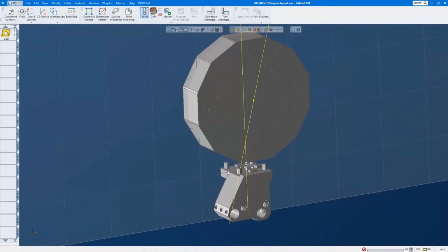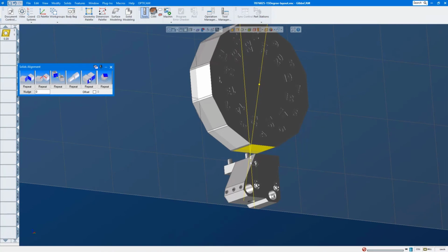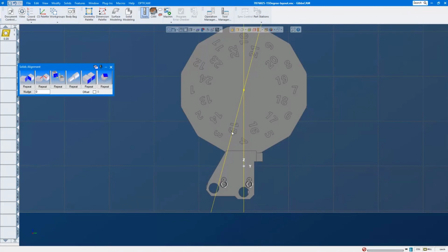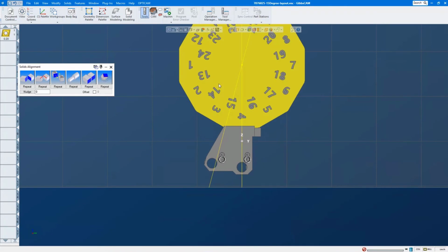If I move this into the position you think it's supposed to be, it can't line up, because even though it's still at 15 degrees, the position is completely different. The distance from the center is different, so this hole actually needs to be moved over here. For this particular turret, you need a different block. There's no other question about it.